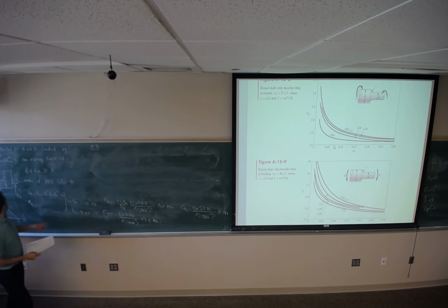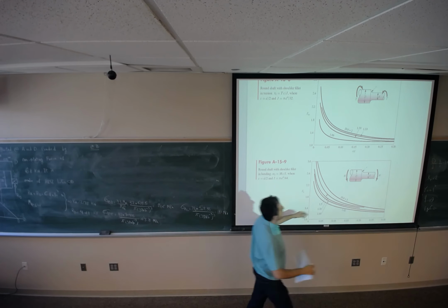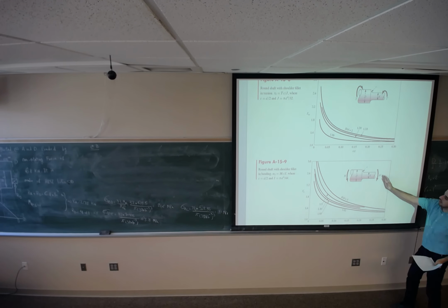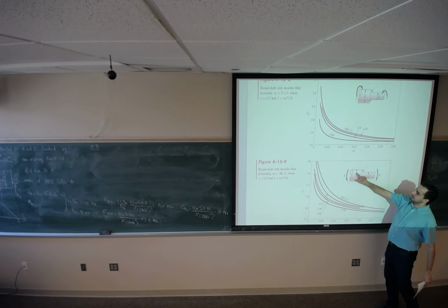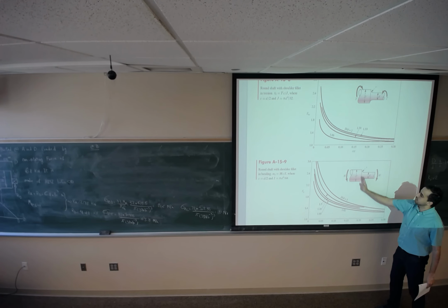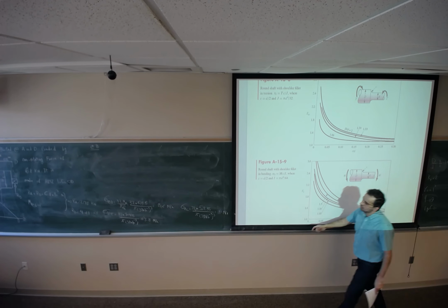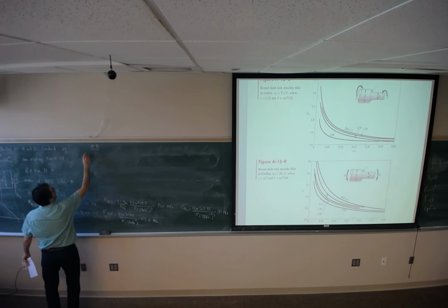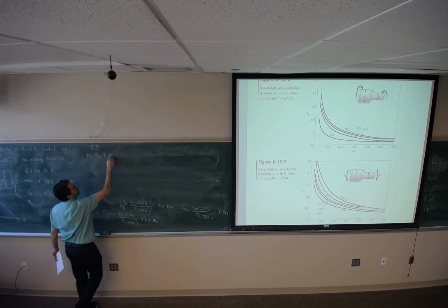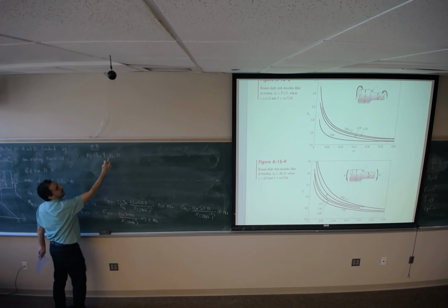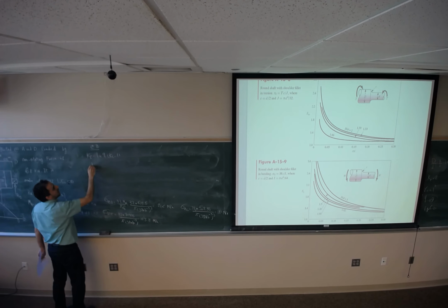This component that I have is something like this. It's only under moment, there is no other load applied to that. I mean, we are looking at the bending moment. We have two different diameters. We are looking for KF at this section. So first thing that I need to find is KT, because we know that KF would be 1 plus Q times KT minus 1. I need to find Q and KT for section B.